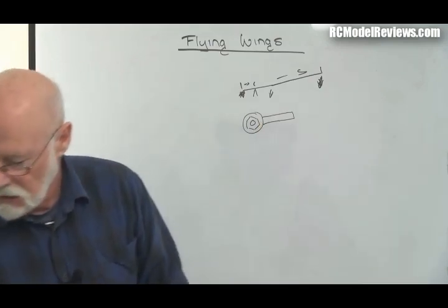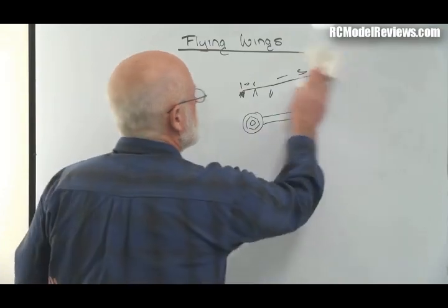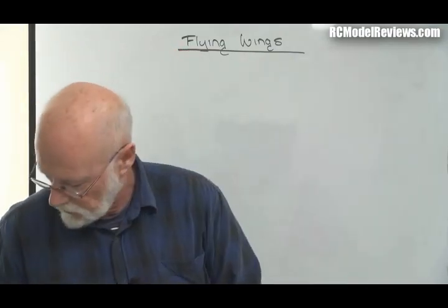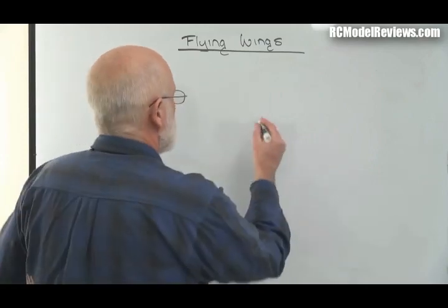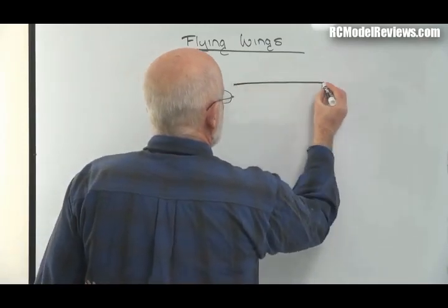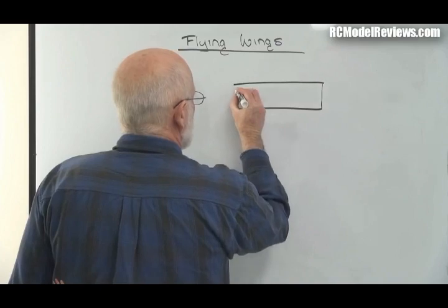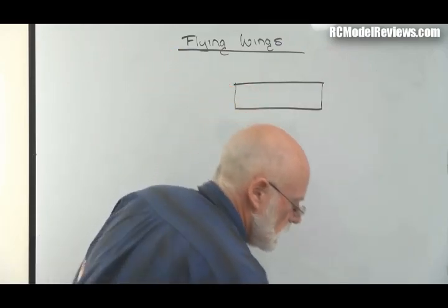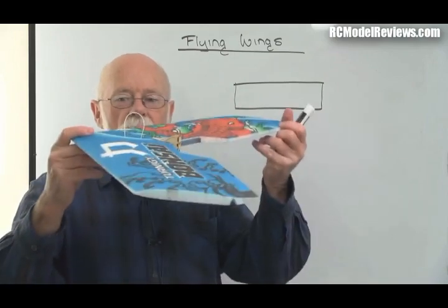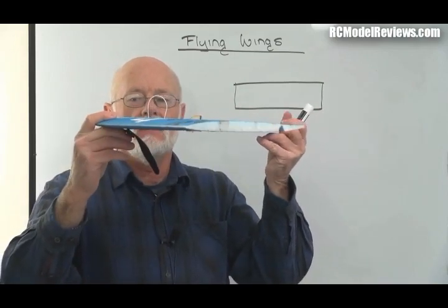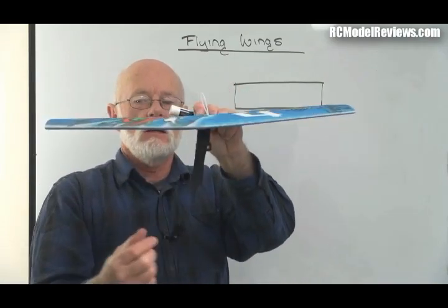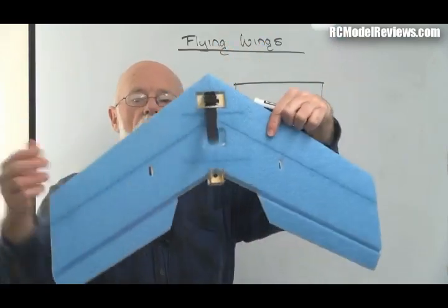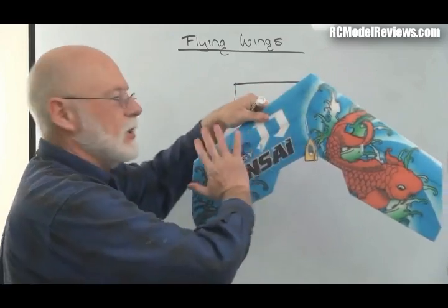Remember that. So let's go back to wings, because that's what we're talking about. But don't forget about levers. Anyway, okay, here's a wing. Looking down on it, we're looking at planforms. Today we're looking at planforms. What's a planform? Quick recap. That's a side elevation, and that's a front elevation. Planform is when you look down on it, or conversely look up from the bottom, but it's the flat. It's when you're looking at it like that.